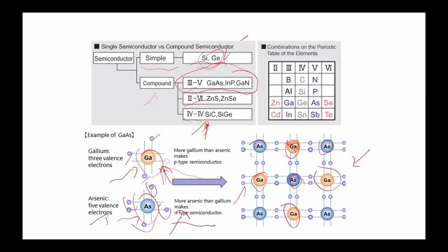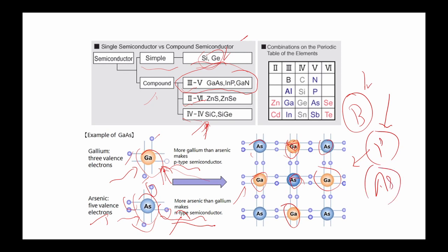It is a bit difficult, but directly we can get the n-type and p-type semiconductors from gallium arsenide. But in silicon, we dope it with boron to get the p-type semiconductor. We dope it with phosphorus or arsenic to make it an n-type semiconductor. Okay, we externally dope it. So now this is group 3 and group 5 that we are focusing on.